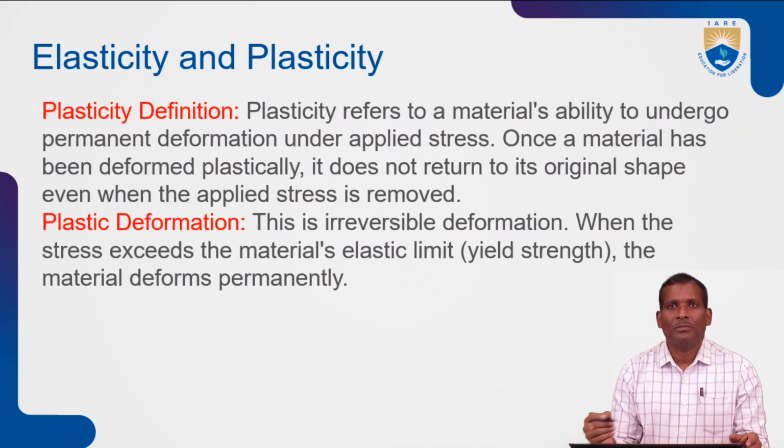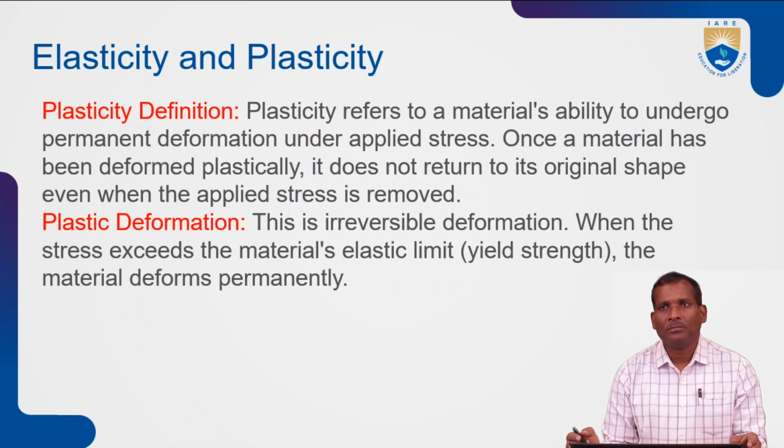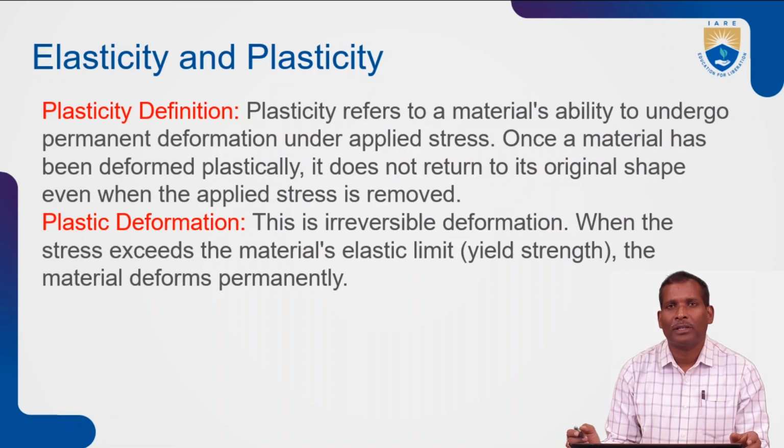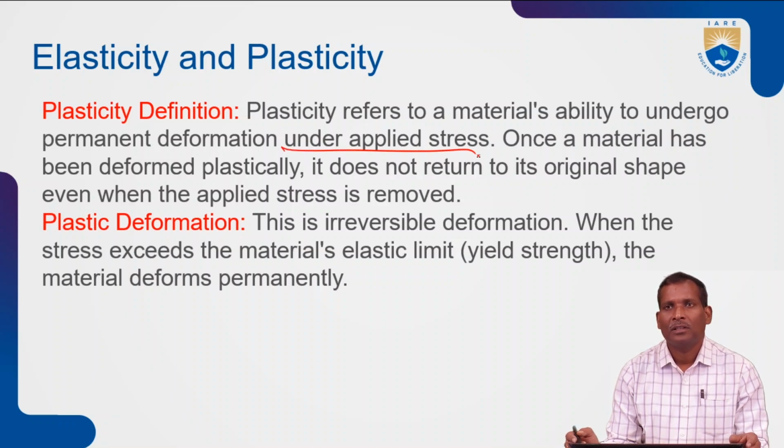Now come to the plasticity property. Plasticity refers to a material's ability to undergo permanent deformation under applied stress. Once a material has been deformed plastically, it does not return to its original shape, even when the applied stress is removed. In the case of elasticity, whenever you remove the load, the material regains its original shape.